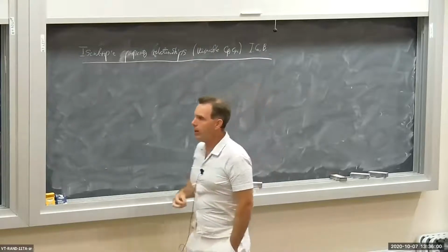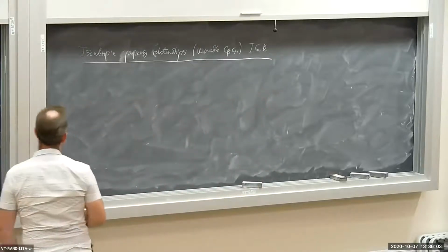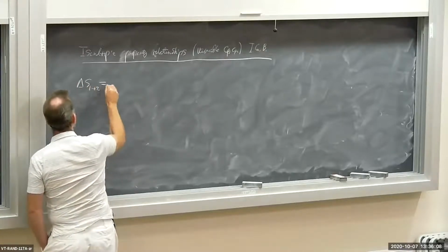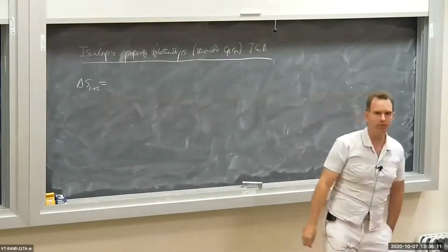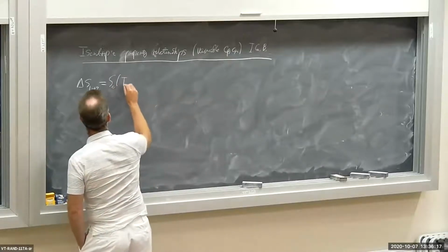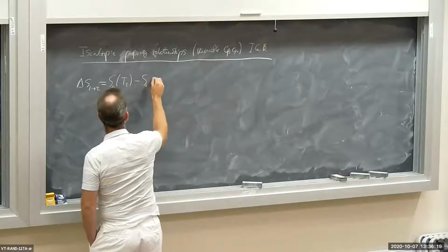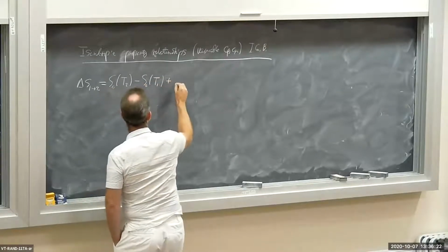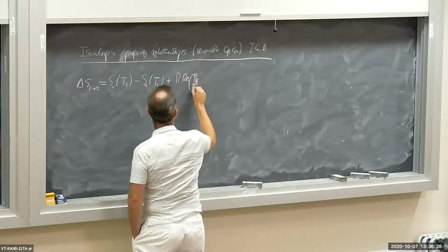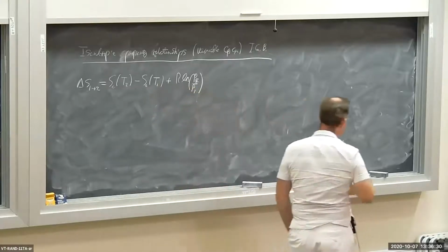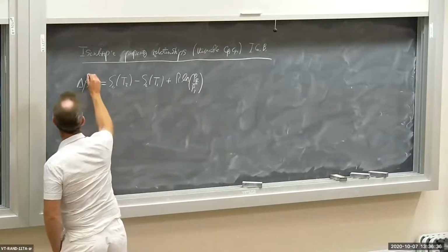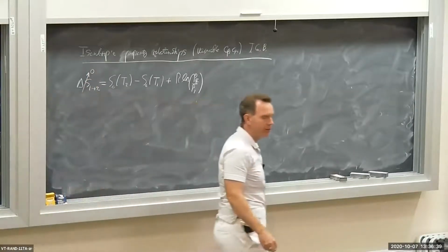Well, let's take a step back here and recall, we had an equation giving delta S for variable specific heats involving those s naught quantities. Remember, it was s naught evaluated at T2 minus s naught evaluated at T1, and then I had a plus R ln P2 over P1, okay? So if it's isentropic, delta S is equal to 0.